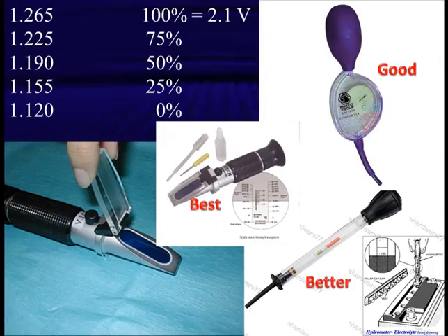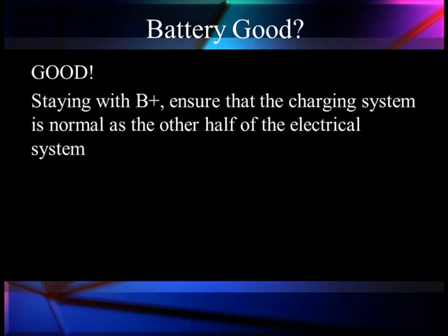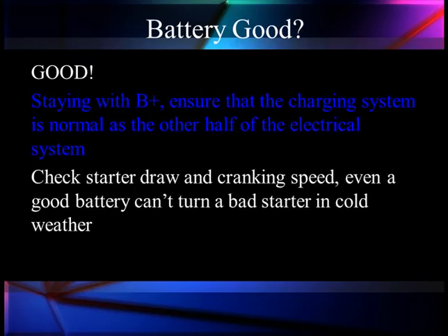We're going one step beyond regular testing. Mind you, we don't recommend this for all batteries, because with sealed batteries this is difficult and we can't do it. We have to do it by open circuit voltage, cold cranking amps testing, and our other voltmeter system. Is the battery good? Is it worth the time it takes to make sure we have a good battery? Absolutely. And staying with B+ to ensure that the charging system is normal on the other half of the electrical system is definitely worthwhile.